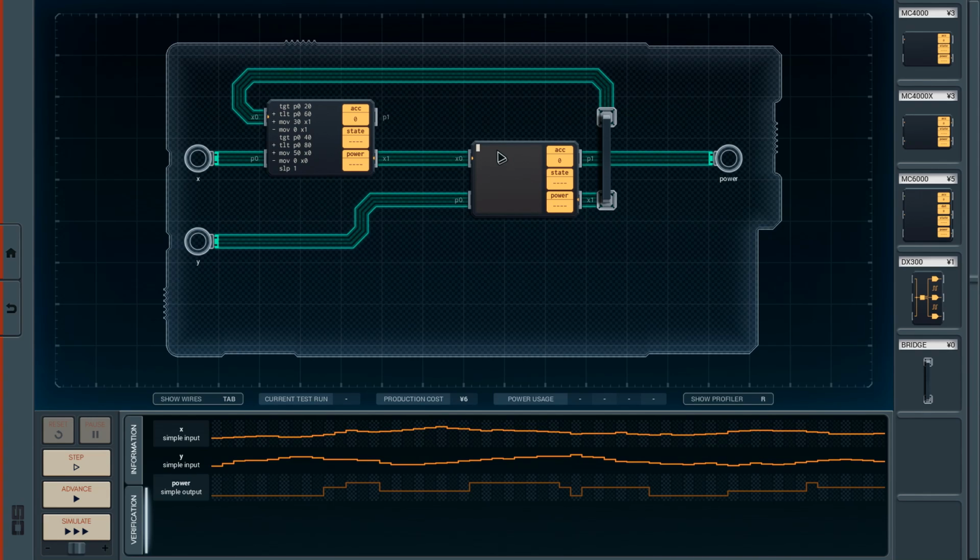Okay, so what do we do? We need to move the input into the accumulator because we're going to have to do arithmetic on this, and that's the only place we can do arithmetic. The next thing we want to do is check the value of X1. So we're going to test if X1 is equal to 0, and if that is true, then it means we're fine. We can just jump over to the end and send the data. So create a jump point here to send, and with the send we will move the accumulator out to P1, and then we will sleep.